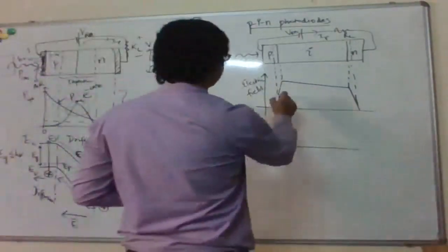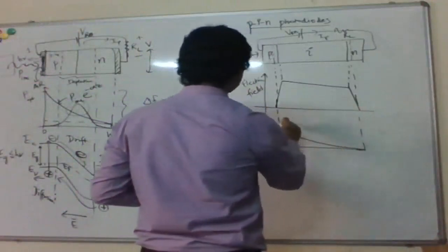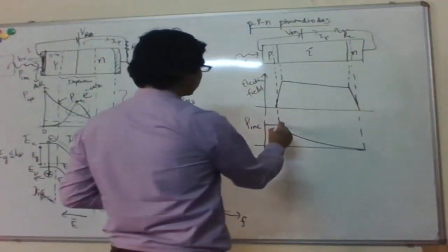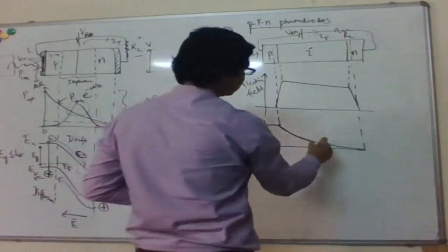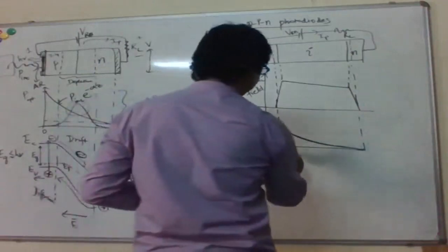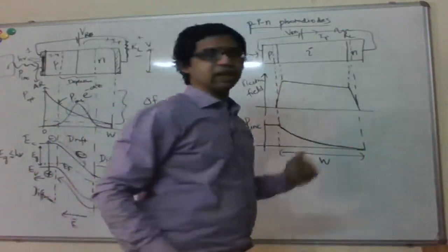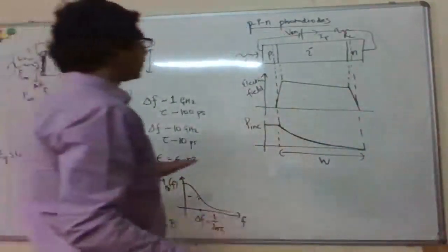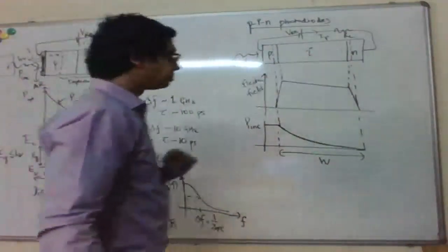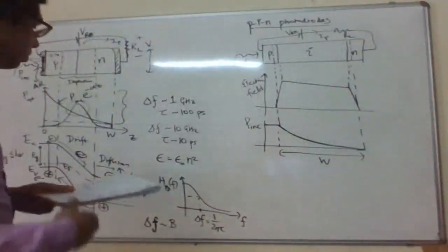Right, so then basically your optical power goes something like that. So this is your incident power, right? And then you start absorbing once you get to the intrinsic region, and then you have this. Okay, so the effective absorption width is basically the width of the intrinsic region, which has high electric field, right? So basically, all your carriers which are generated due to absorption of photons are all moving with a drift velocity. So you sort of eliminate the diffusion component altogether,